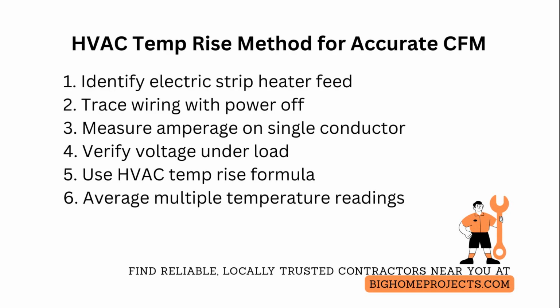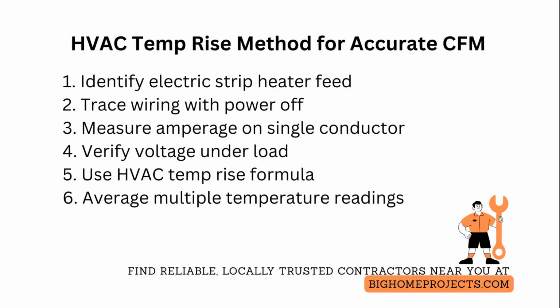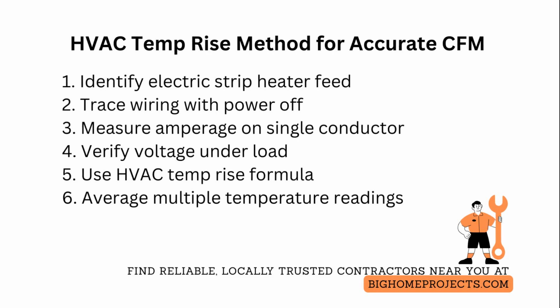If you cannot isolate the strip heater feed because of shared neutral or multi-wire bundles, remove the access panel and clamp the individual insulated conductor. Never clamp multiple conductors at once, or you will read net current and get near zero.